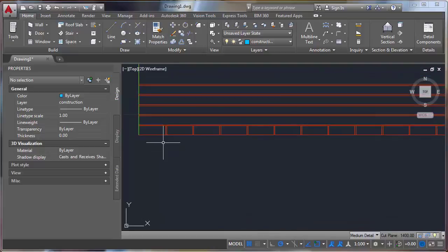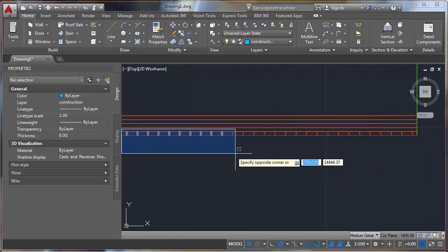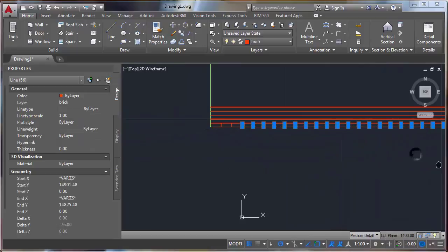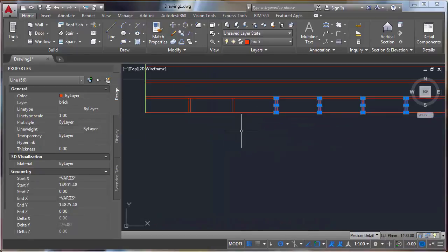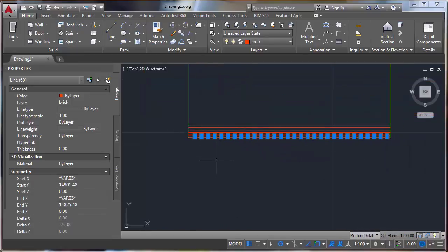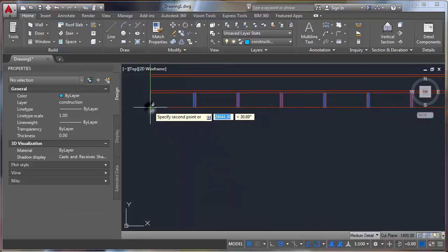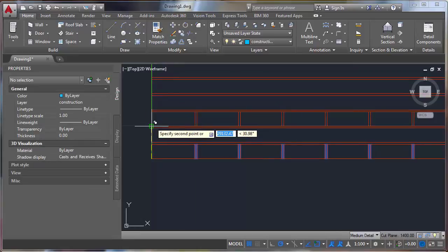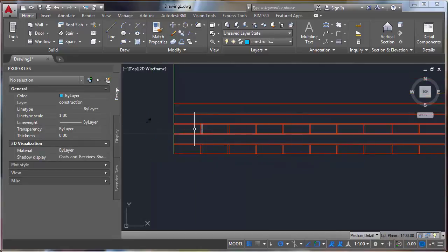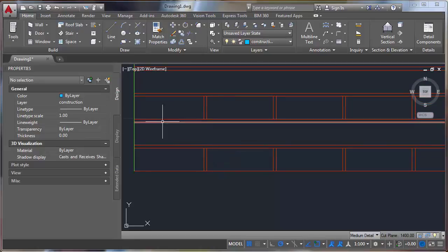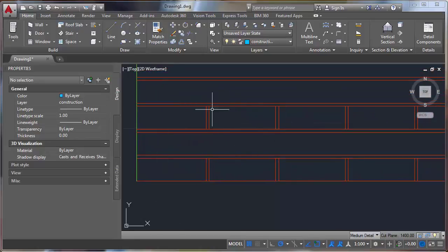And I could now just take all of these and I'll hold shift and put these into the selection. One annoying thing about, not shift, no, don't hold anything, about AutoCAD is if it's not on the screen it won't select it. So now I need to copy these up or array them up, but I want to only array or copy them every other row. Right? If I'm making a running bond, I actually have to repeat this, but offset shifted the length of the brick for the second row.